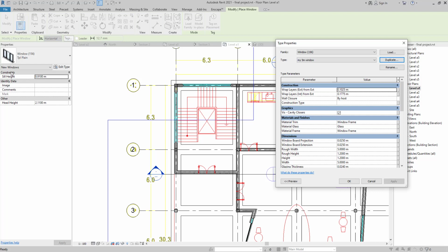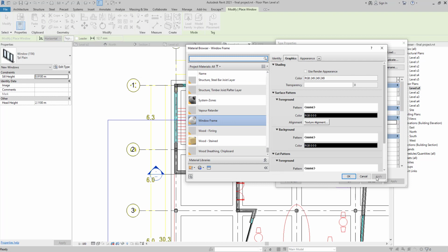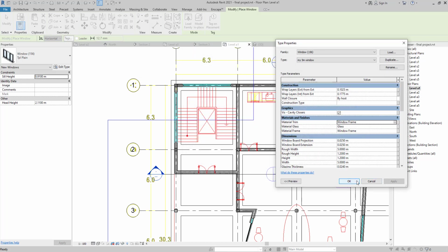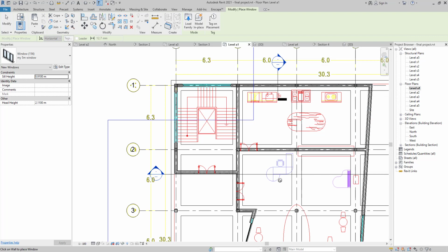and we are going to use three slide out glass with three framing, because it is better. It's 5 meter, it's already a very wide and huge space, so we need to consider three panels for calculating the cost, and for safety insurance we need to use the three glass panels. So I'm just going to use the 5 meter, change the measurement, and I can change the framing material. So let me check what's the material. It's white, it's alright. And after that, just click OK. The next editing for our elements is going to be about sill height.